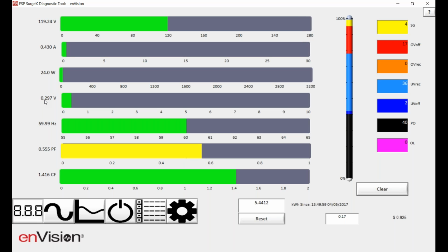And on that note, I want to mention that the voltage we're looking at here is the 60 hertz power line frequency neutral to ground voltage. Our products filter out a lot of the high frequency neutral ground voltage content, and this measurement here is really the 60 hertz. And like Vince said, if anybody wants more details on acceptable ranges and things, please get in touch with Vince or myself later. A high value could indicate various things. The most common would be excessive loading of the circuit. Another could be something miswired, or a bad or loose connection requiring an electrician to chase down and correct. But I just wanted to make that comment on the neutral ground voltage.